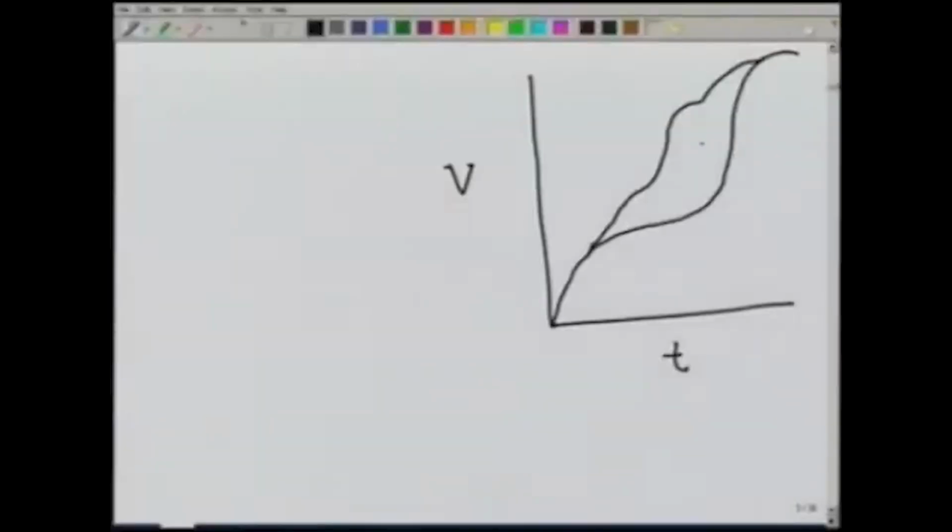In this case, we cannot use the same method which we used earlier, because now we cannot draw a parallel line at the point. So, we have to estimate the maximum ordinate. For example, in this case, this S may be the maximum ordinate. So, for a variable demand, we have to compute the maximum ordinate, and that will be the required storage S.